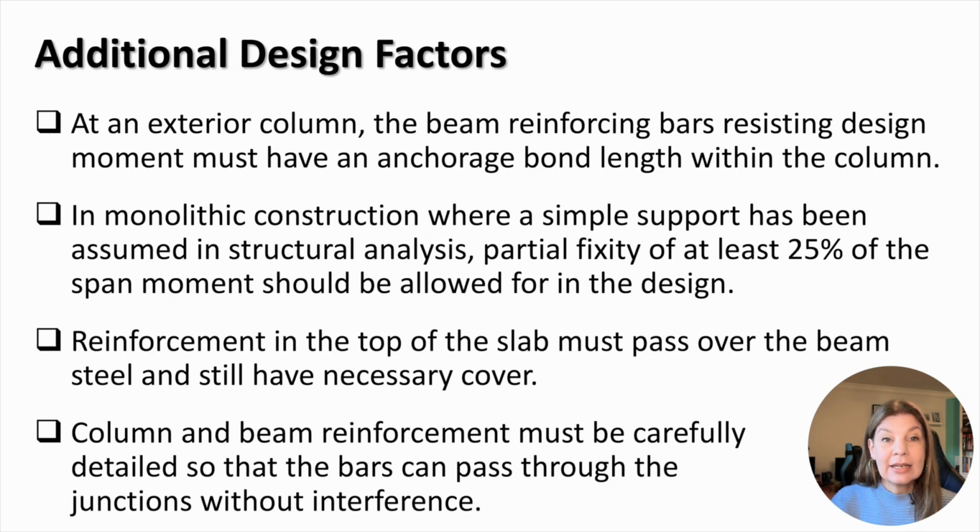Let's consider a few additional design factors. At an exterior column, the beam reinforcing bars resisting design moment must have anchorage bond length within the column. This means that the longitudinal bars should not stop at the column face. They should be bent and made to continue into the column, as can be seen in this picture.